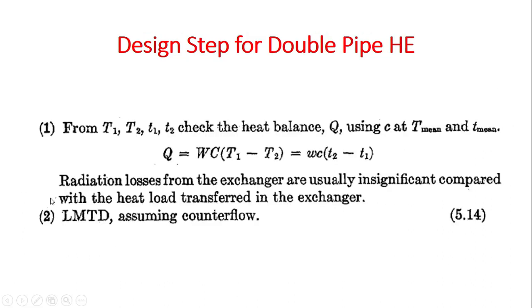So the first step is you will be given the inlet and the outlet temperature for the hot fluid and the cold fluid. So check the heat balance, right? And using specific heat and the mean temperature, or it could be the caloric temperature, or the average temperature. Radiation losses from the heat exchangers are usually insignificant compared to the heat load transferred in